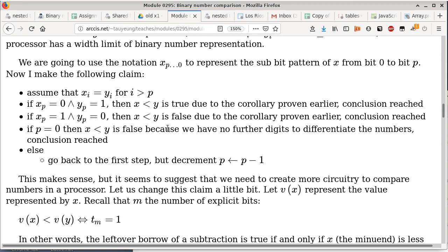We make use of the sign bits, but we do not change the sign bits. So the overflow is just to show you if you can trust the comparison or not, whether you can trust the sign bit. If there's an overflow, the sign bit would indicate the actual opposite of what it should be indicating. Okay, so it is the opposite then, if there is an overflow. If there's an overflow, then the sign bit is opposite to what it should be. Okay, thank you. That's what I was asking.